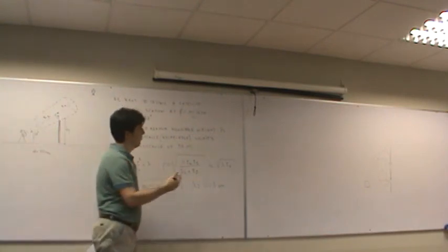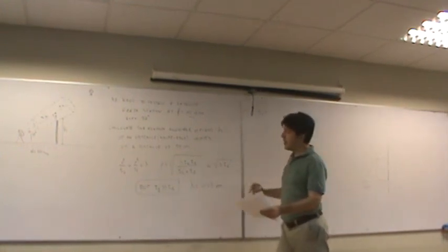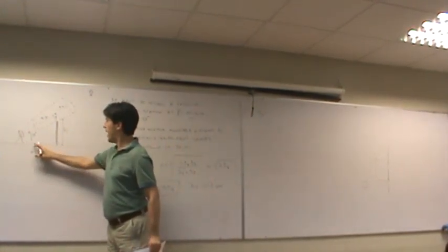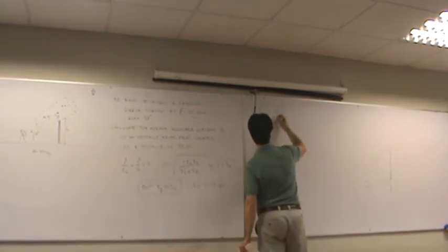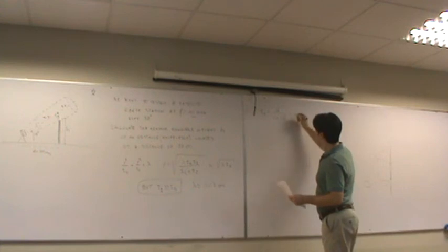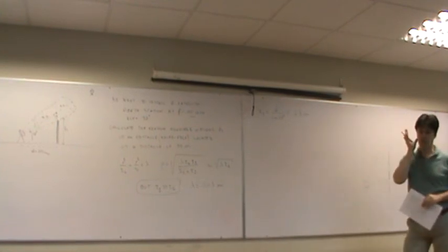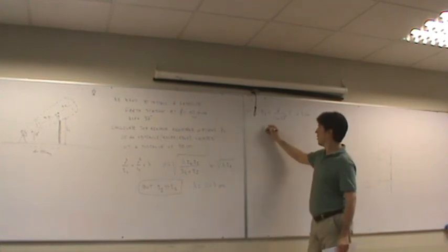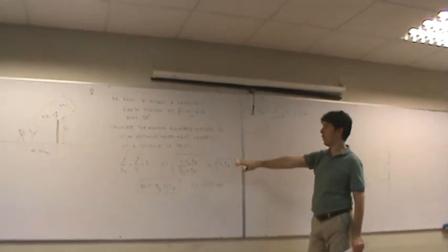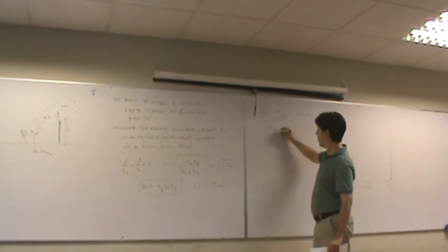R1 is the distance d divided by the cosine of this angle. So it's about 63 meters. Now the size rho around that point of our Fresnel ellipsoid will be 1.4 meters.